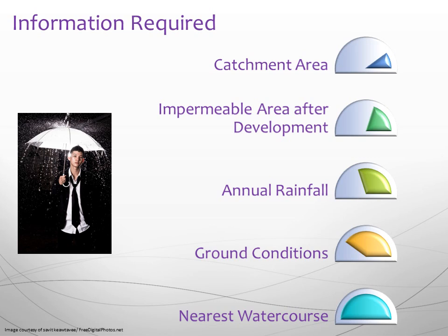The impermeable area is usually determined by adding up the total road surface, footpaths, building roofs, driveways, parking areas and any other hard standing intended for the developed site. If the development includes permeable design for car parking, footpaths, etc., this needs to be considered and not included as part of the impermeable area.